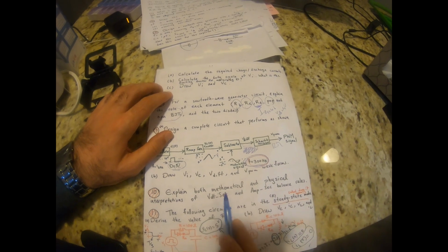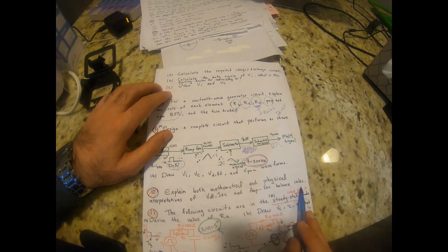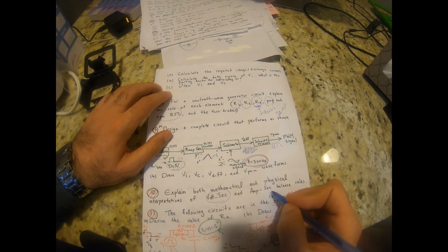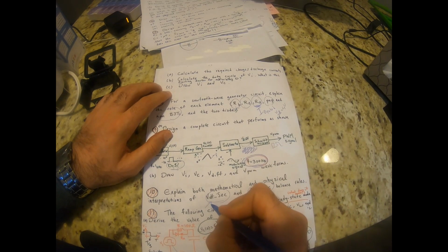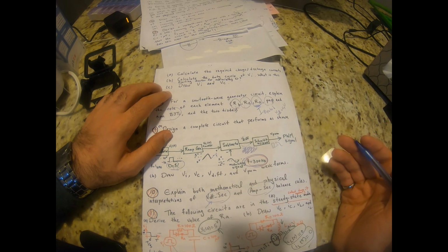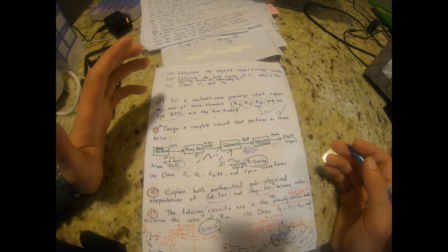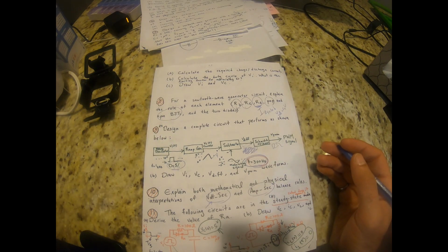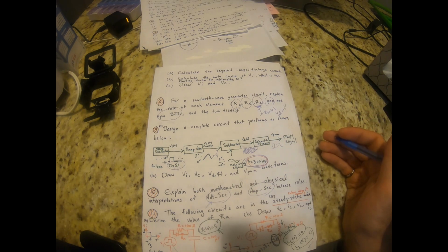For volt second and amp second balance rules, I already mentioned that. For volt second, it means that the flux going into an inductor, the average of it over one period, is going to be 0. Or at the same time we can say that the energy that goes into an inductor is the same as the energy coming out of it if we are in the steady state.